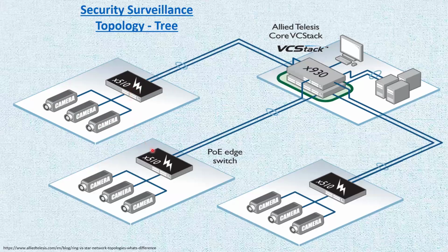Right? And then in another area, you can set up another sub switch. If those are far enough, you can connect that to a media converter, which is going to convert to a fiber optics signal, and then another media converter that's going to convert that back. And you can connect it to another switch, which is plugged into that main DVR.